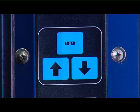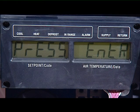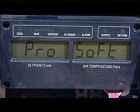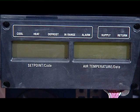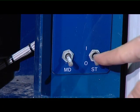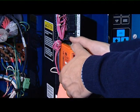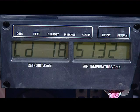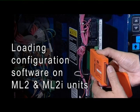The display will show once again, Press Enter. Press Enter. The display will show the message Pro Soft. This message will flash until programming is finished. Wait until the display shows the message Pro Done. Switch the unit off. Remove the adapter with the card. Switch the unit back on again and verify the software version has been loaded by selecting Code 18.